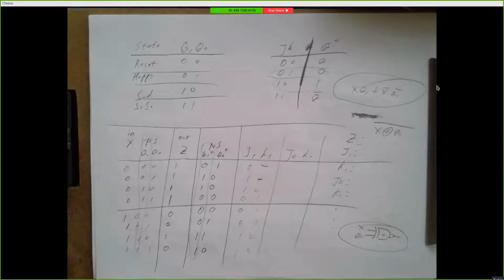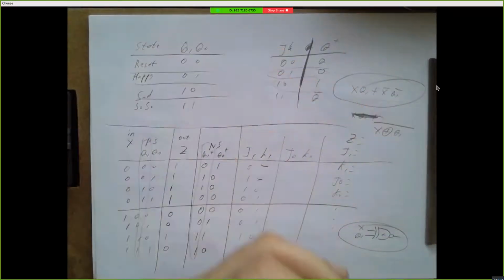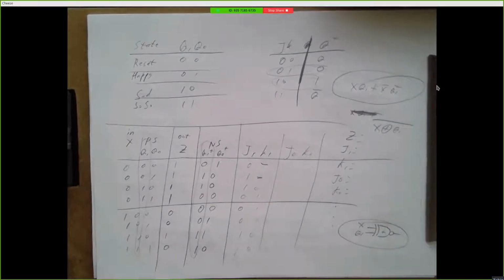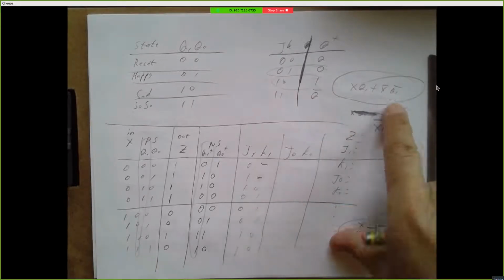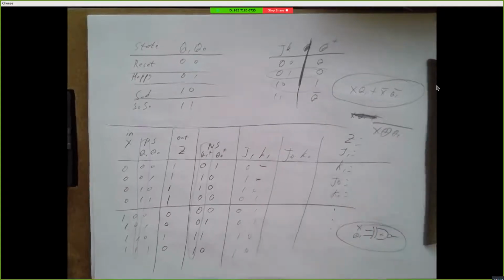Okay. If you're doing this for your own purposes, you don't have to show all your work. But for homework, you always want to show your work, particularly when you're doing sum of product, K-map, sum of product, minimize sum of product, another sum of product, and then bang, an exclusive NOR gate suddenly appears in your circuit. You want to at least show the step where you said my input is equal to this, which is also equal to an exclusive NOR. So that's an important piece.